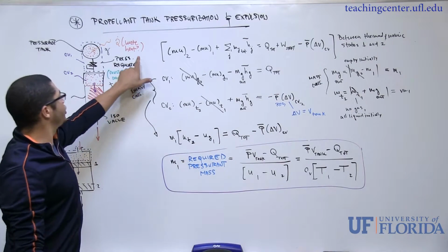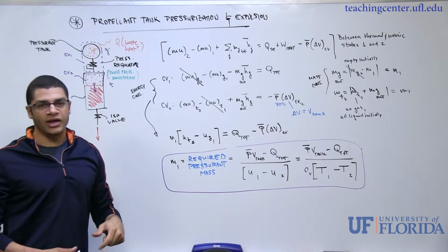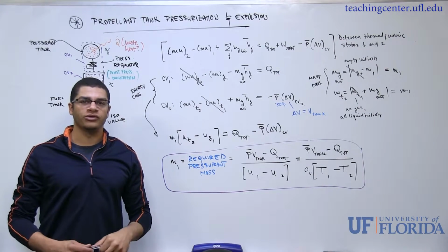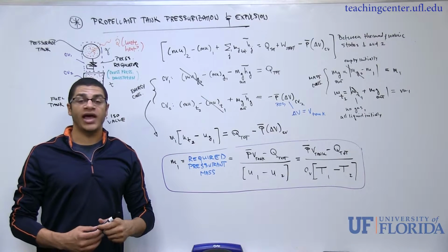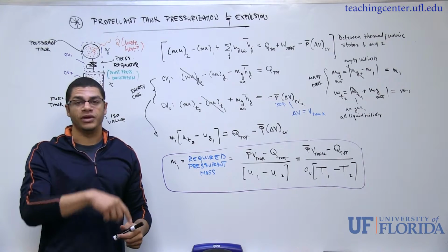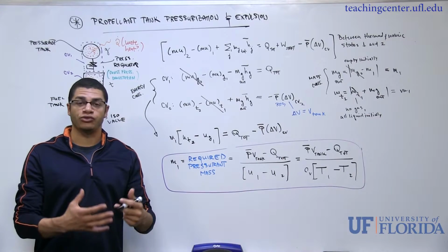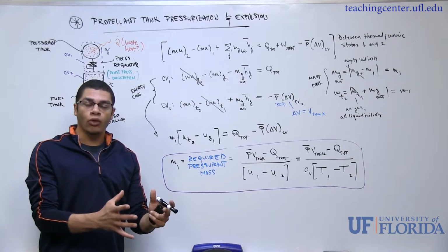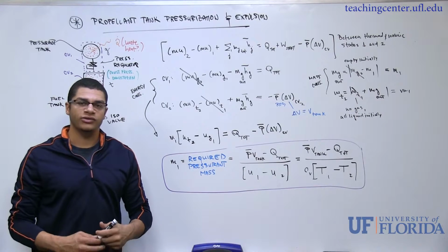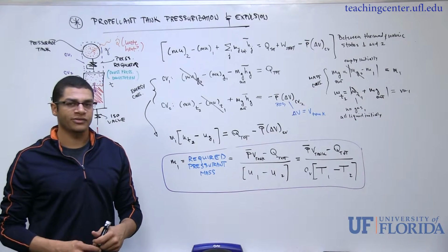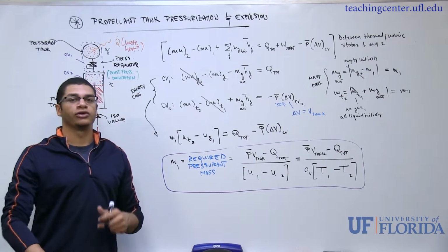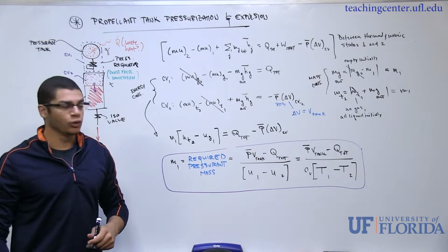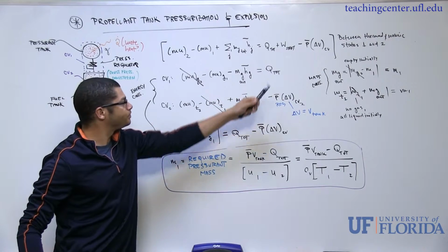Like I've listed over here, I said maybe there's some waste heat. For a particular example, in a rocket propulsion system, some of the pressurant gas is heated prior to being sent to the pressurant tank, or maybe the tank is heated at some point or even downstream of the tank. And so this adds a little bit more energy to the gas that it may give up during the expansion process and in expelling the liquid from the actual fuel tank. So this will come into play later.